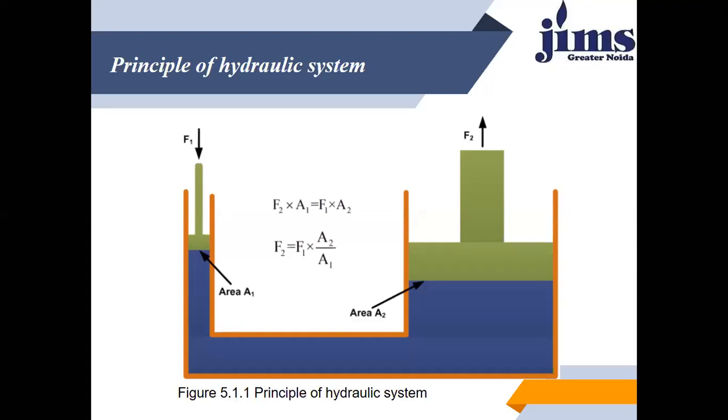No problem. So I think you all are getting what I'm telling and what I'm teaching you. I'm telling you, you must be aware of petroleum-based hydraulic oil, because it may cause a fire hazard. That's why, in order to stop the fire hazard, we have to use a special kind of fluid, a special kind of oil whose upper temperature limit is beyond the temperature we attain during the work, so that the fire hazard will not occur. And this may cause some cost.